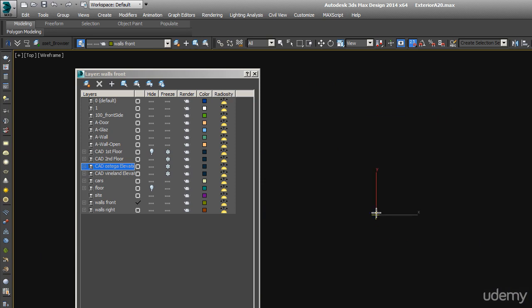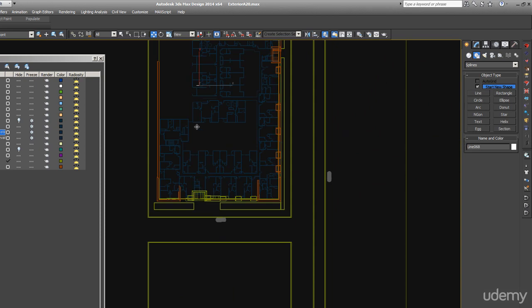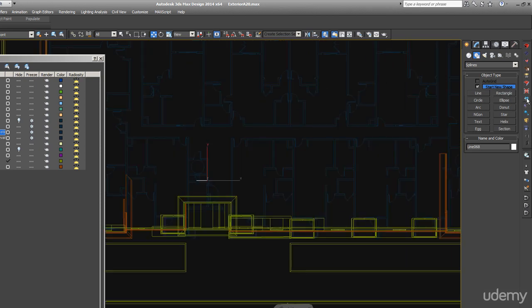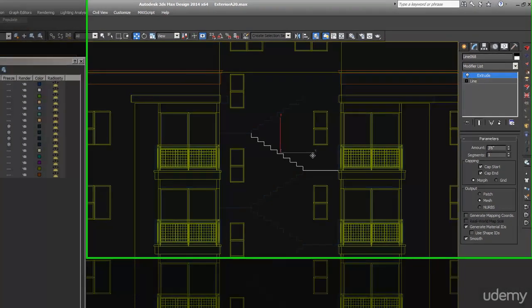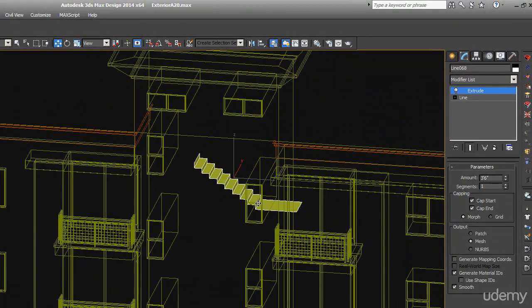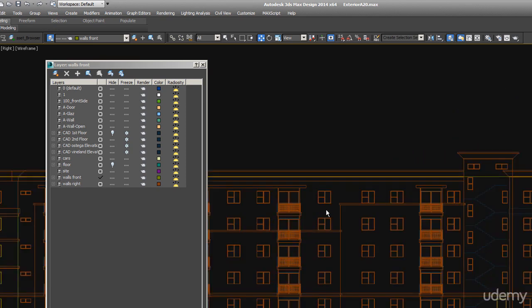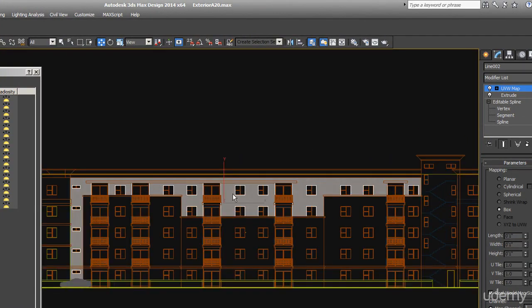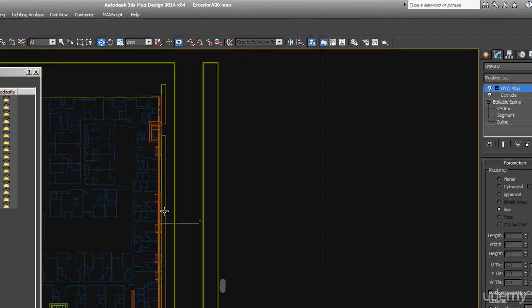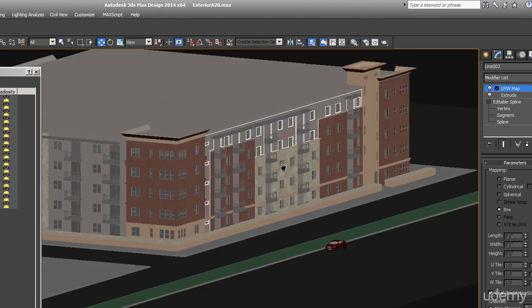Okay, now I have this line here sitting out here in this plane, and I will have to move it up using the top view to the correct place, and then you can just extrude it as stairs or whatever it is you're trying to do. So that's how this whole entire model is created. Usually start by referencing the elevation and making these big shapes. This one, for example, is just a big chunk of wall. And then you go to top view and place it in the correct plane there. Eventually you get an entire building.